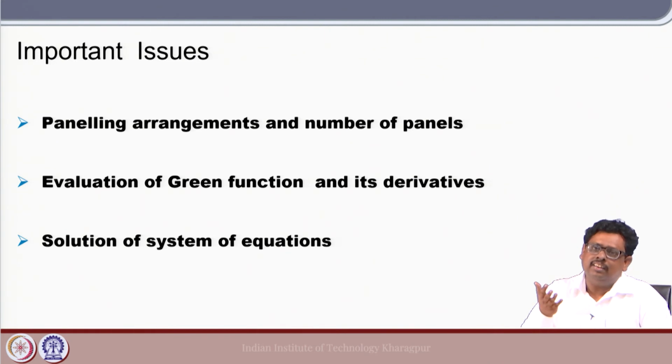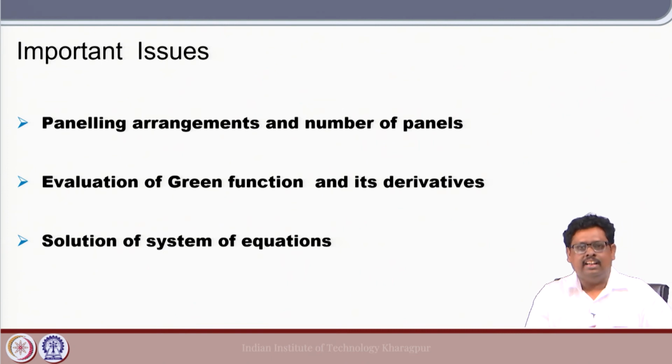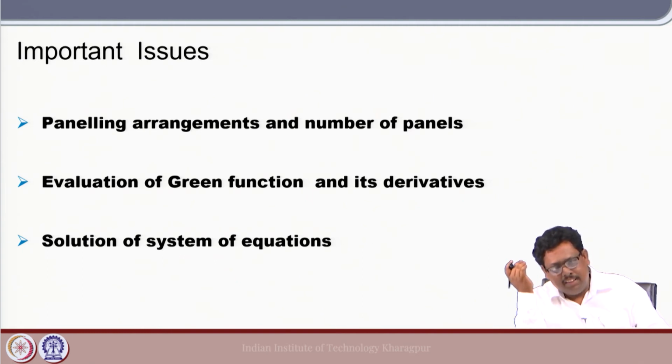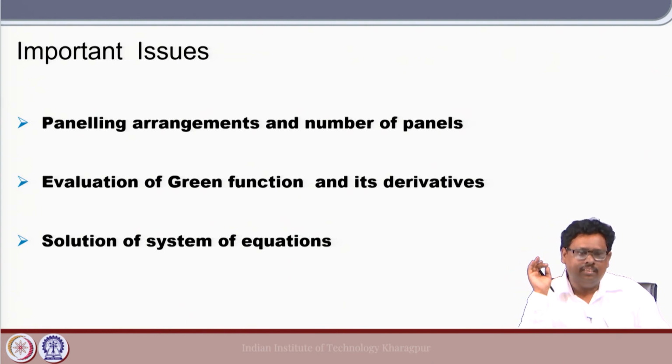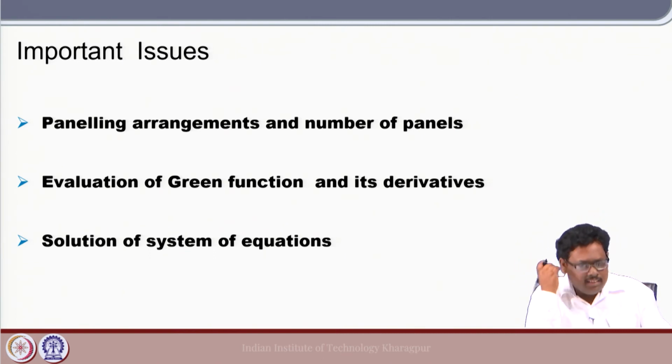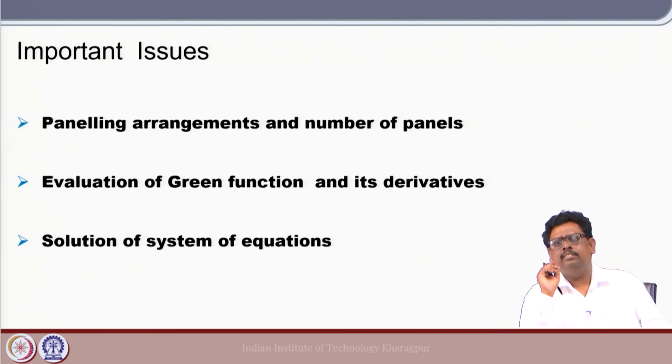Again, the evaluation of the Green's function derivative we discussed a lot, so let us not discuss it again. Then we have the solution of the system of equations. Nowadays, as I said, this is not a big deal, because we have sufficiently stable solvers available. We can pick any one and solve the equation. Mostly the understanding of the paneling arrangement and the correctness of the Green's function will be the deciding factor whether your code is good or bad.